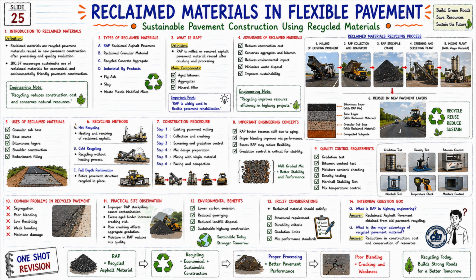Now let us look at the 8th topic. Eight: important engineering concepts. RAP binder becomes stiff due to aging. Proper blending improves mix performance. Excess RAP may reduce flexibility. Gradation control is critical for stability. Now look at the well-graded mix concept below. Better gradation, better stability. And pavement performance also improves.